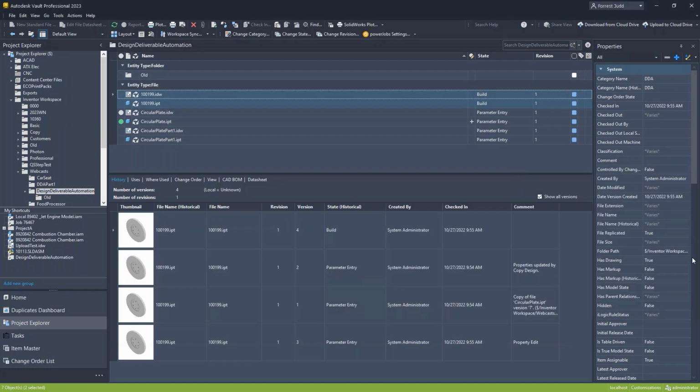One more question, can you automate an autosave feature for IPT and IAM files? Not with iLogic. I guess technically you sort of could if you did it in response to an event, but then you'd be saving probably far too often. I suppose you could do that as an add-in running in the background with a timer, and it could periodically save. That gets a little risky, and I think part of the reason there's no autosave in Inventor is because sometimes saving can take a long time.